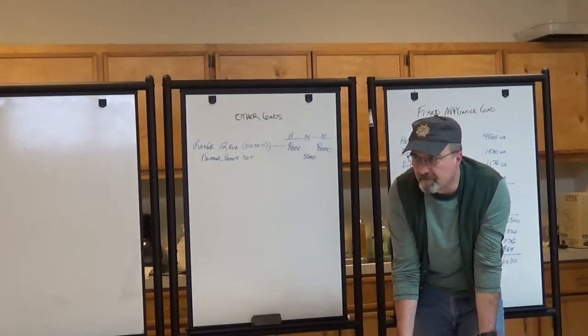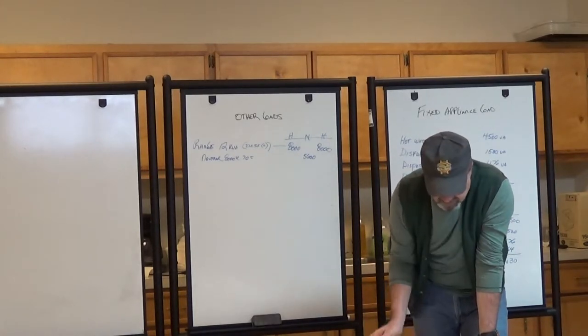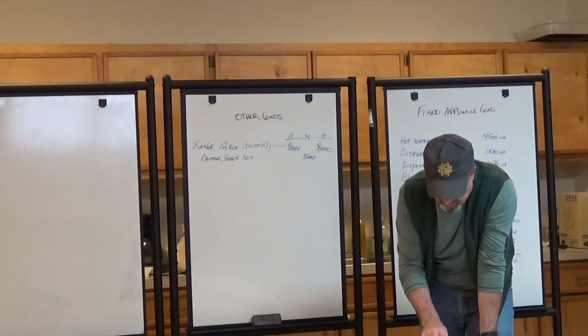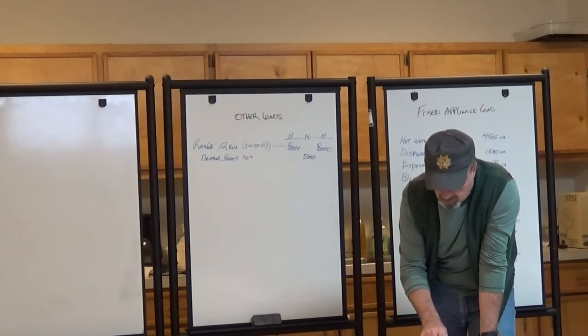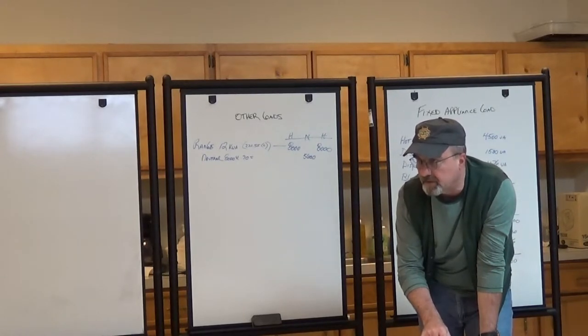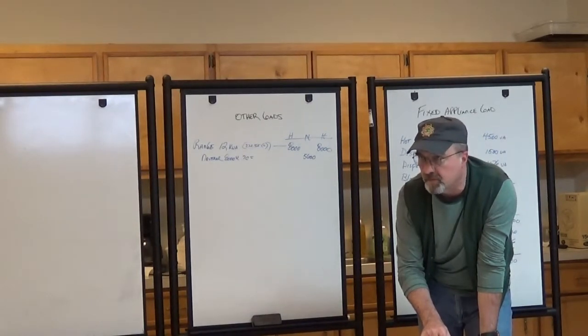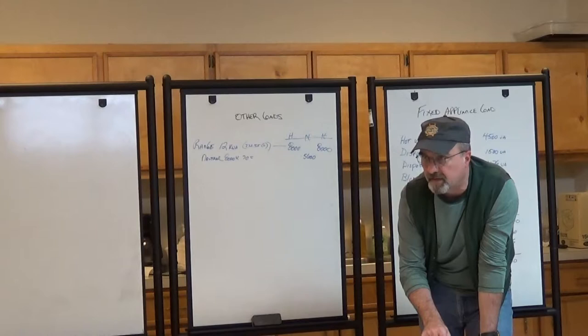It would be 4,500. It says the load for household electric clothes dryers in a dwelling unit shall be either 5,000 watts VA or the nameplate rating, whichever is higher. So if the kVA is only 4.5, it's going to be 5,000. We have to give a demand of 5,000. Right.